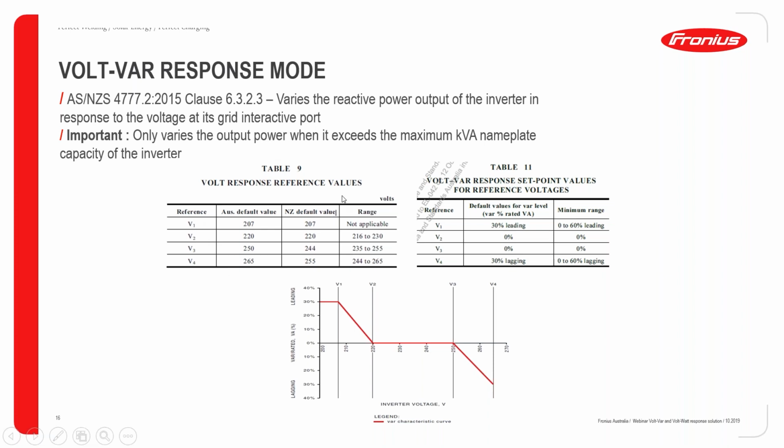understand this table. So you have 4 voltage values, and then we have 4 power factor values given in the table. So what you're seeing over here on our inverters, we have the nominal voltage value of 230 volts. So that's with the Fronius inverters. We always consider 230 volts as the nominal voltage value.